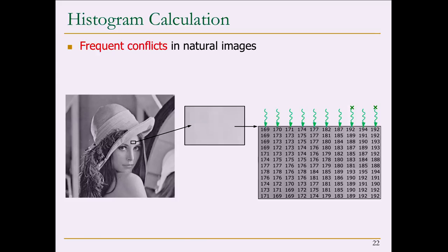They both are accessing at the same time, so only one of them can do it in each time. So we have a serialization. Now think about what the serialization entails. Reading 800 cycles, modifying, writing 800 cycles, reading again 800 cycles, and so on. So this can take a lot of time.